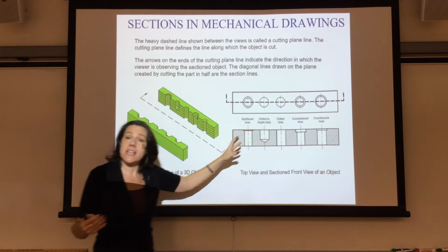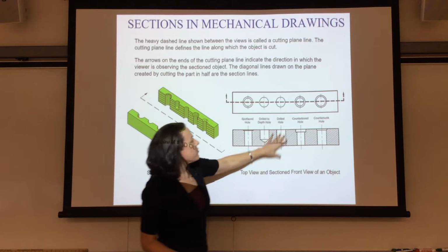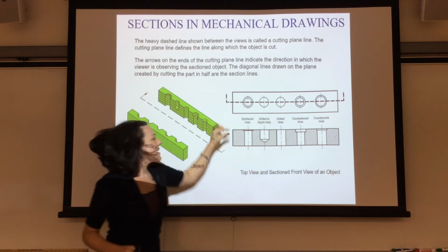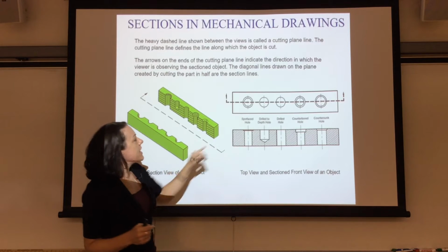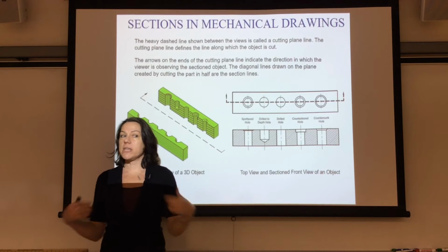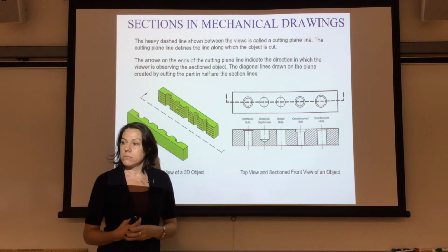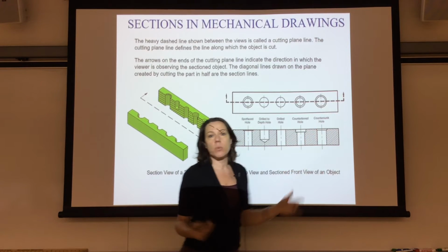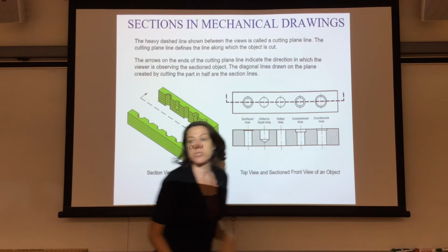Drilling a hole to a depth that has a tapered end. So on your drawings, you have to tell everybody how deep you want the object to be cut through. Then you've got a drilled hole that goes all the way through, and then you've got a counter bore. Now the counter bore is actually a little deeper in the head of it than the spot face. Okay? Now here's the thing, does this circle and that circle look any different? How would I know the difference if I was looking from the top view? I wouldn't until I cut it in half and I could see a section view. Okay? And then the last one is a countersink. The countersink actually has tapered. We've all been to Home Depot and we've seen the screws that have the tapered heads, right? Those are the countersink holes.